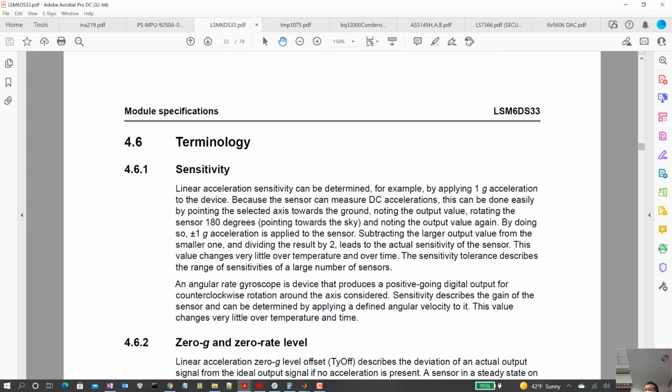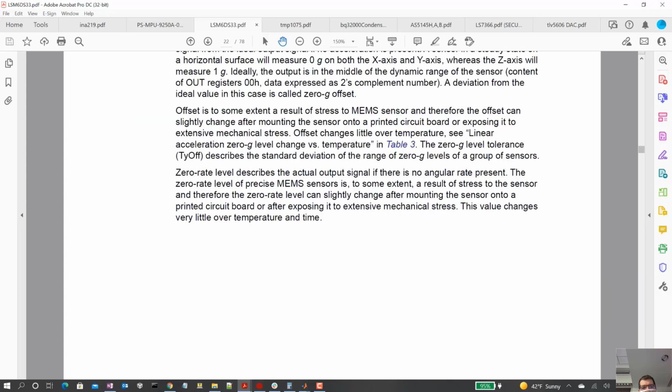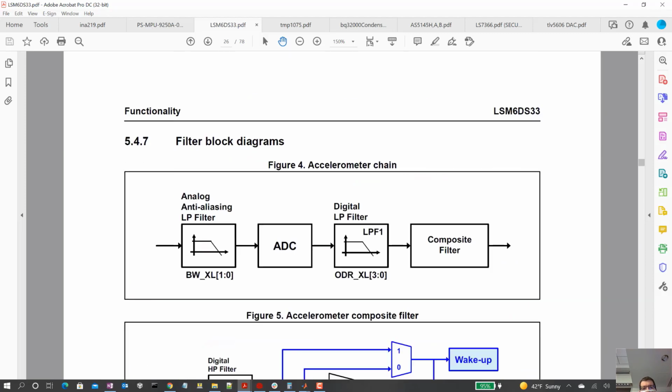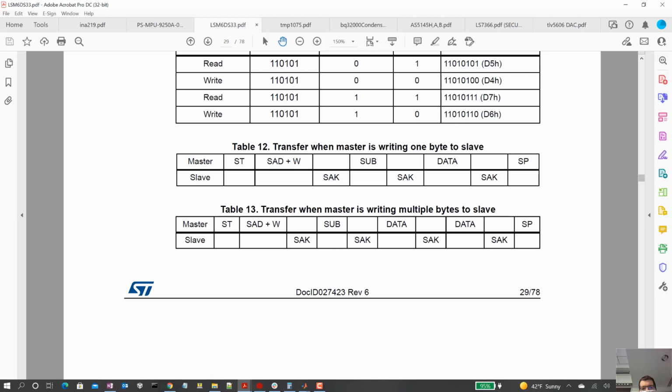Normally you hardly ever will use I2C where you use every address, all 126 addresses, right? Or actually 127, because 0 is not a normal address. 0 is an address for all the devices in I2C. If you want to talk to all the devices for some reason, you can write out to address 0, and all the chips will accept that. Okay, anyway, let's get back down to these timing diagrams.